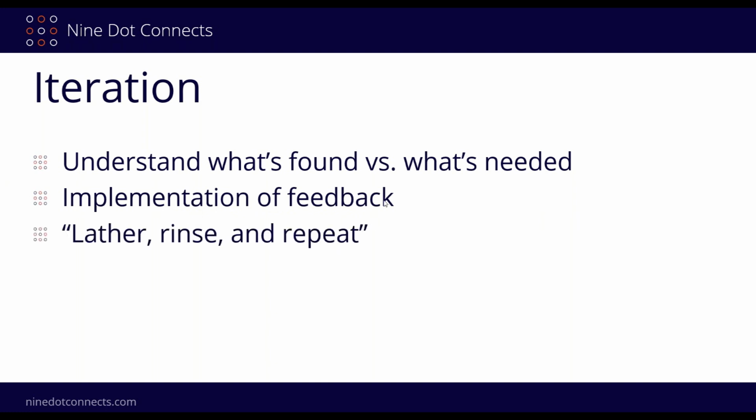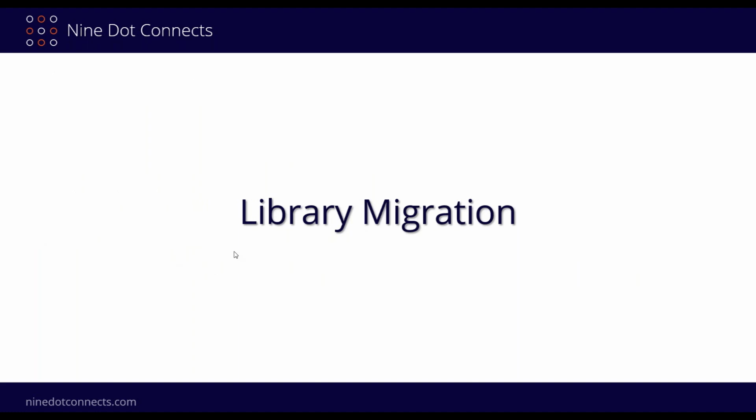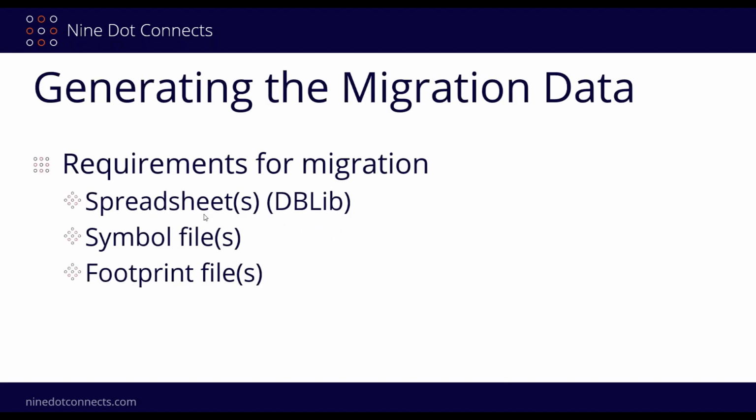Because you know that you just got to find some humor in all of this that needs to be done, because there's a lot of work, as you can see here. And then lastly, the migration. So up to this point, all we've been doing is trying to put together a solid Excel sheet that looks like a database library, but we haven't got it to its destination yet. And migration does require a few things. Number one, some type of spreadsheet or an Altium Designer, if you have it in an Excel and treat it as a database library. That works really well for migration.